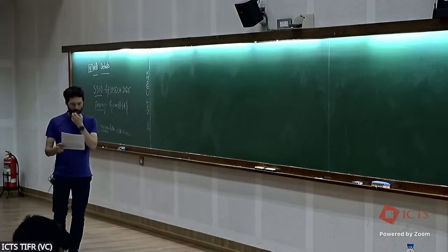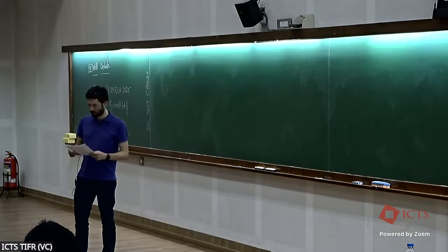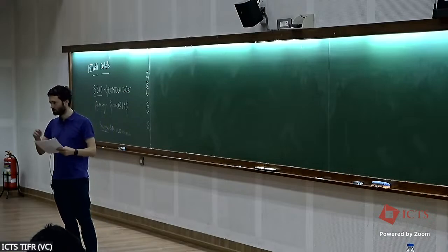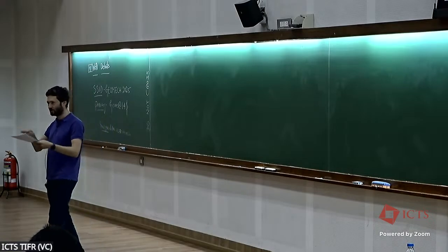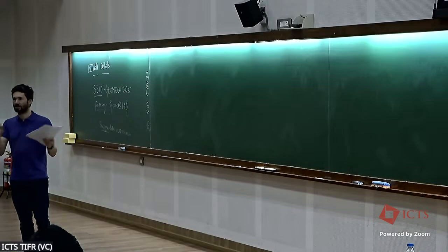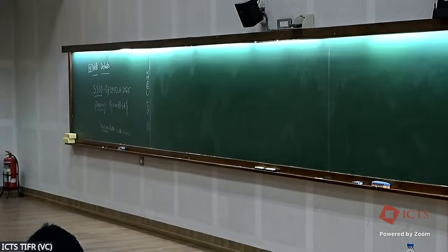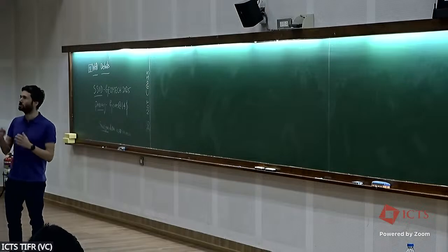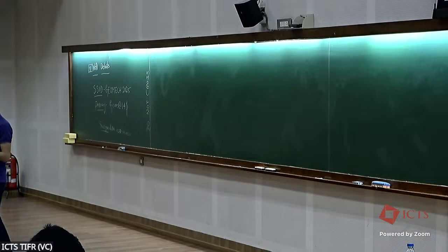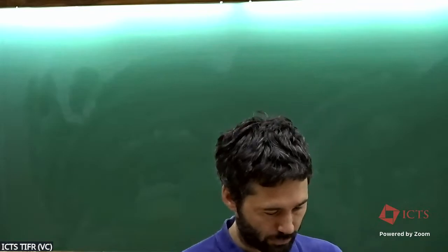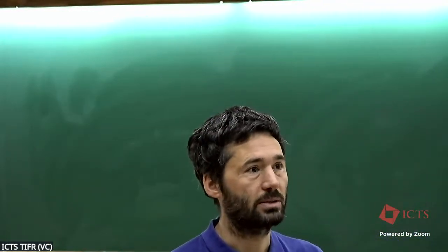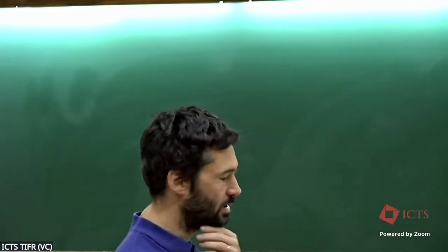Since lots of plate theory is interested in flat plates, and because the stretching modulus is large compared to the bending modulus, there is a special interest in the surfaces that are isometric to a plate, so surfaces with vanishing Gauss curvature.